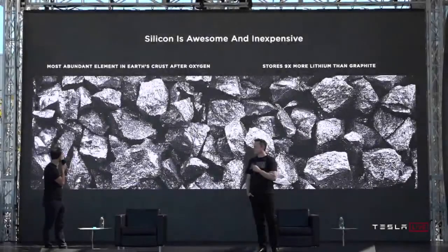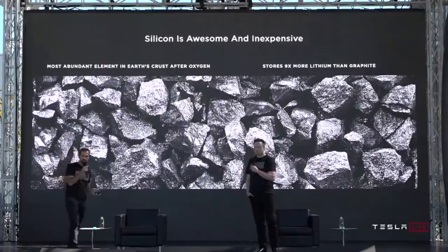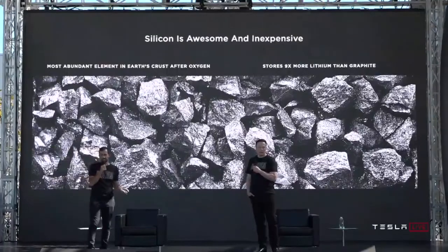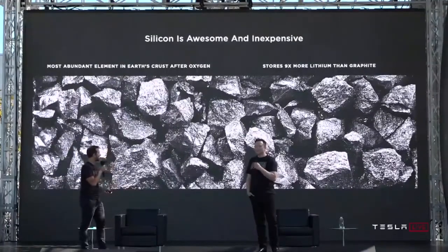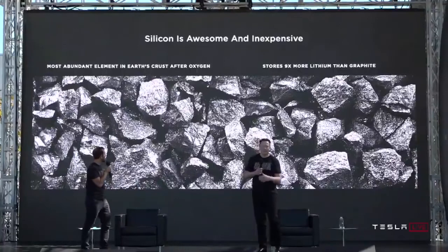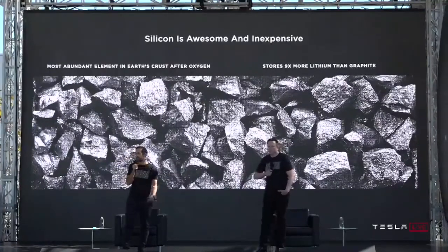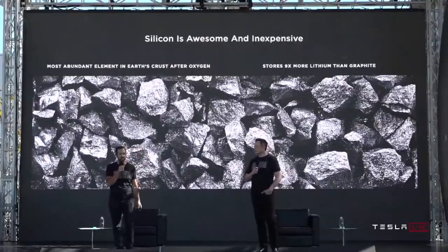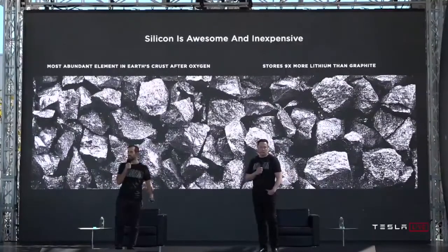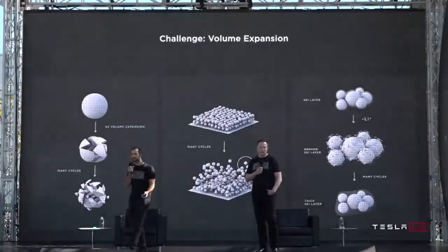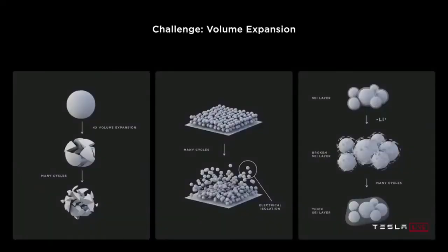And finally, what about silicon or solid-state batteries? Will they reduce the need for graphite? Well, it appears that as you add more silicon into a graphite anode, the energy density increases, so silicon doping is actually beneficial for graphite. And I have even seen reports that anodes with 15 to 20% silicon doping are rivaling the performance of what solid-state batteries should be able to do.